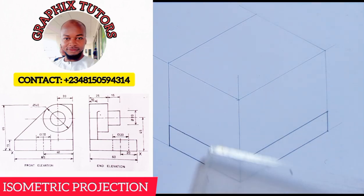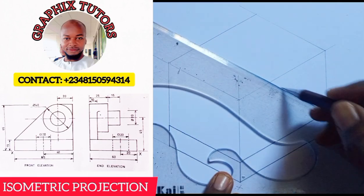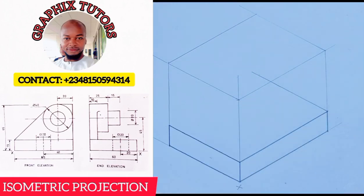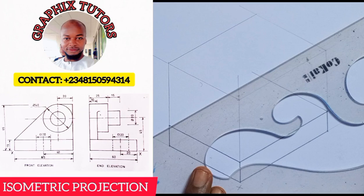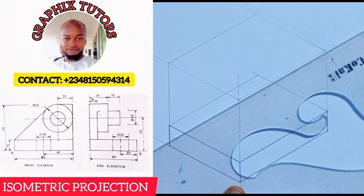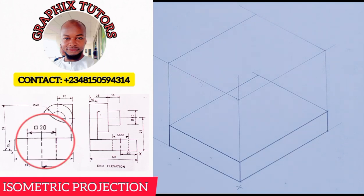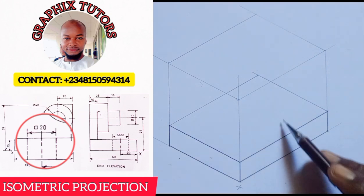Then I will just connect this to this. From this point, I will draw my line. And from this point, I'll draw my line too. Hope you can see that. So there's a hole in between. How did I know the hole? This hidden line you're seeing shows that there's a hole in between somewhere around here.